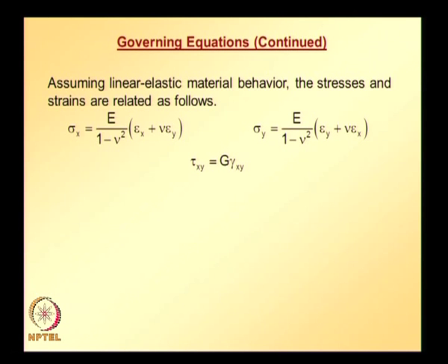So, under plane stress conditions and under linear elastic material behavior, stresses are related to strains through these three equations. Three components of stresses are related to three components of strains through these relations, which we can write in a matrix form.